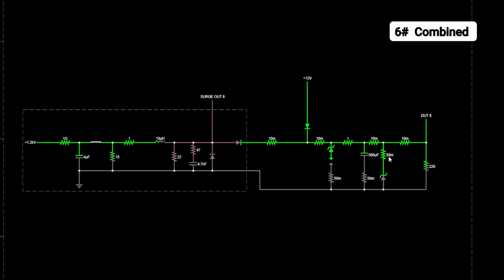And there are a lot of variations to this circuit that you can do. You can have a full pi filter in here to make sure that not only are you helping with the surge event, but you're also helping to prevent any ringing and to provide a good noise filter both downstream of your circuit and back upstream on the conducted noise if you have a buck converter or something that might be spewing noise back to the circuit.